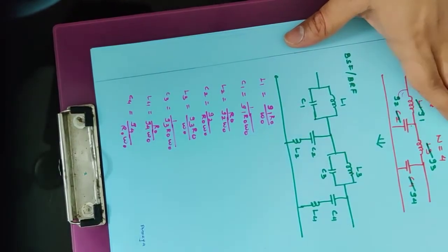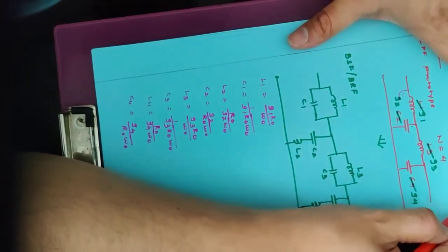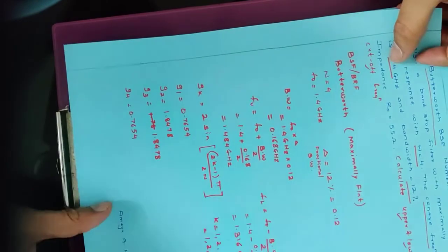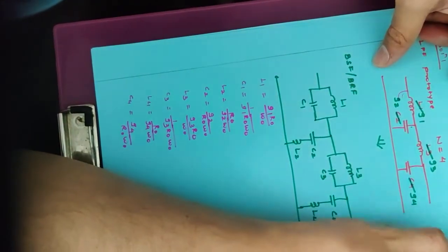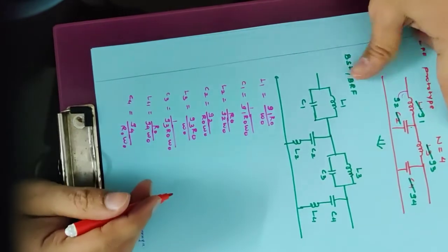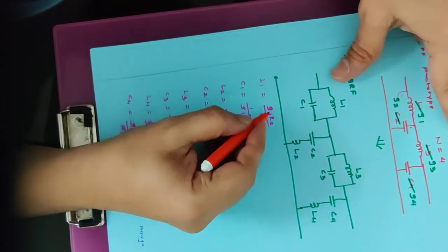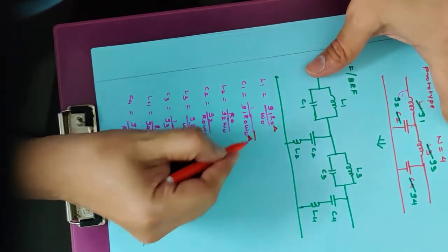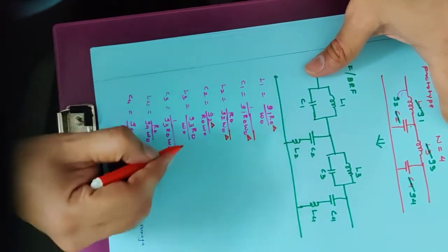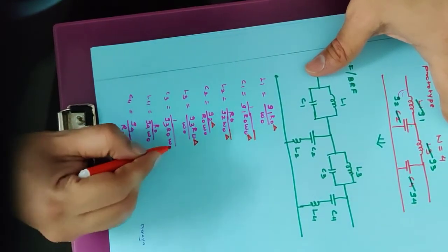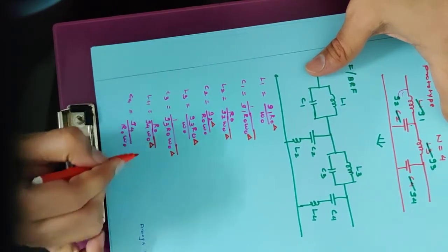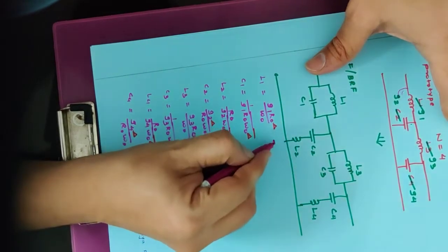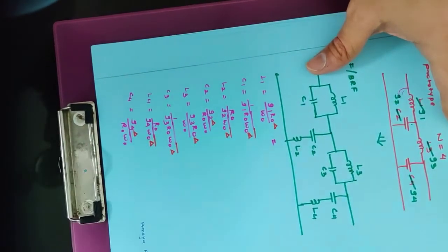And now this delta in the design we have considered as 0.12. So this delta for the design of band stop filter is placed along with G. So here I will have delta over here, so we'll calculate these components by substituting values of the G, R0, delta and omega naught.